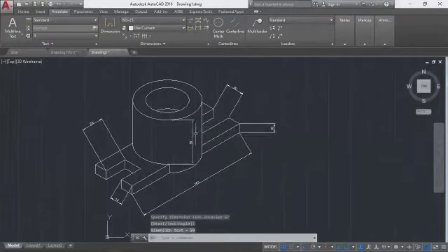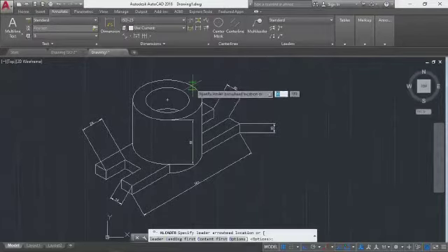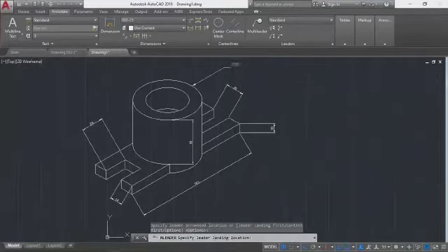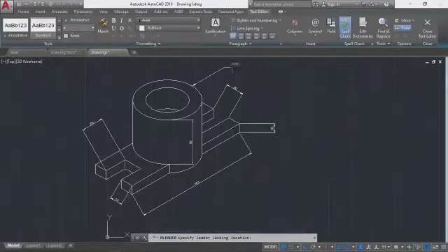That's for that. Then for this radius, you can come over here, over here, over here, over here. Yes, multiple leader. Click on your multiple leader. You touch this first, nearest. You click enter. So you specify your radius. Your diameter, you'll see symbol here. Come over to symbol. You pick diameter and you specify 64. That's the diameter.